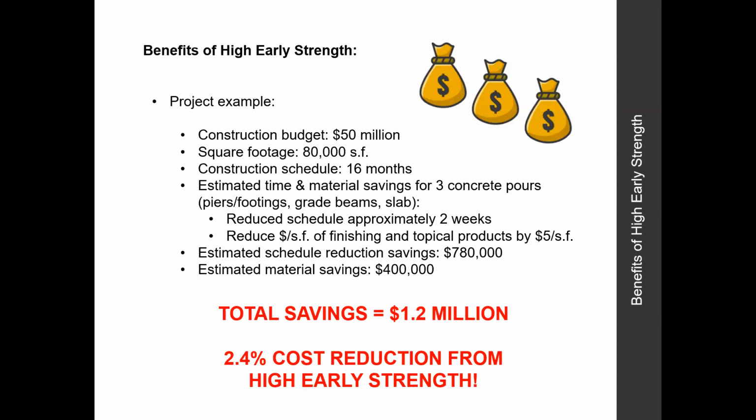Sure. With a lot of the clients that we work with, when they've got their initial budget projections to meet low carbon concrete requirements, primarily up in Canada, where the low carbon regulations go into effect in the next 6 years, across the board, everybody's increasing their concrete budgets by about 20% and assuming that their construction schedules need to be lengthened because of delayed day of strength.